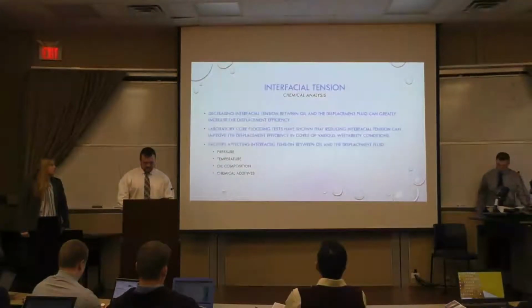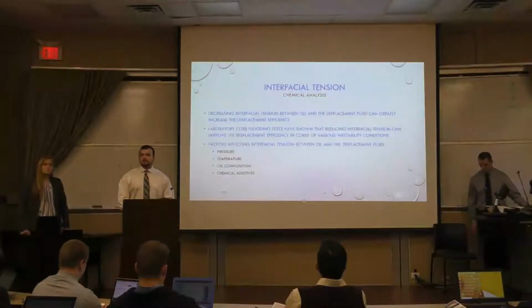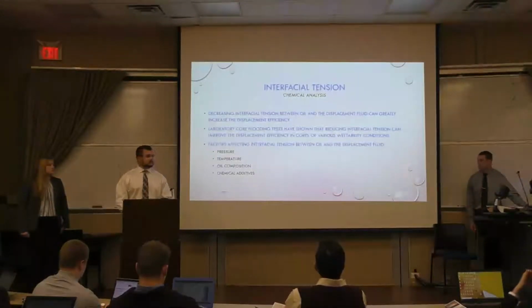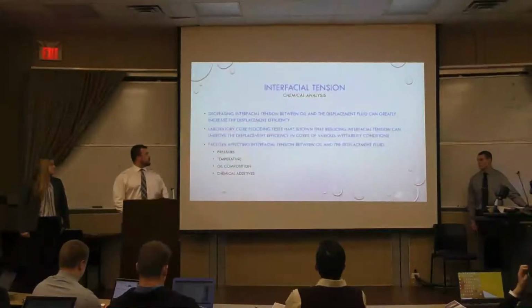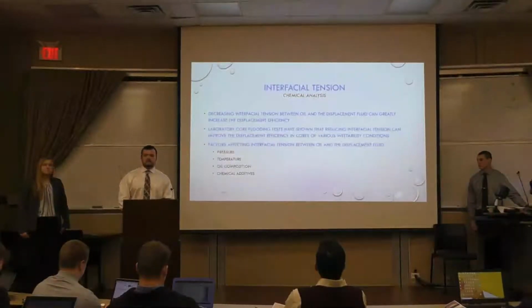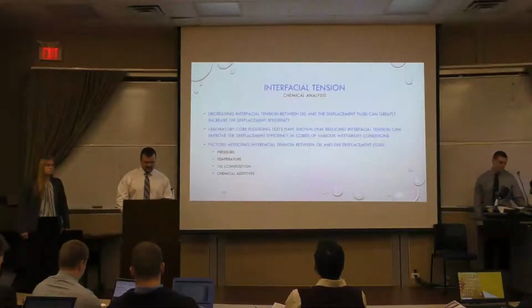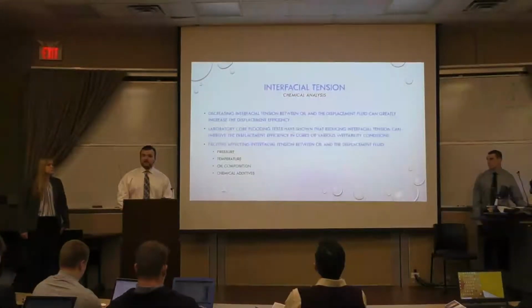The next thing that they look for is interfacial tension in the reservoir, and decreasing the interfacial tension has been shown to greatly increase the displacement efficiency of the injected fluid. Laboratory core flooding tests have shown that reducing interfacial tension can improve displacement in various wettability conditions, either oil wet or water wet. And some of the factors that affect the interfacial tension are pressure, temperature, oil composition, and the chemical additives present.